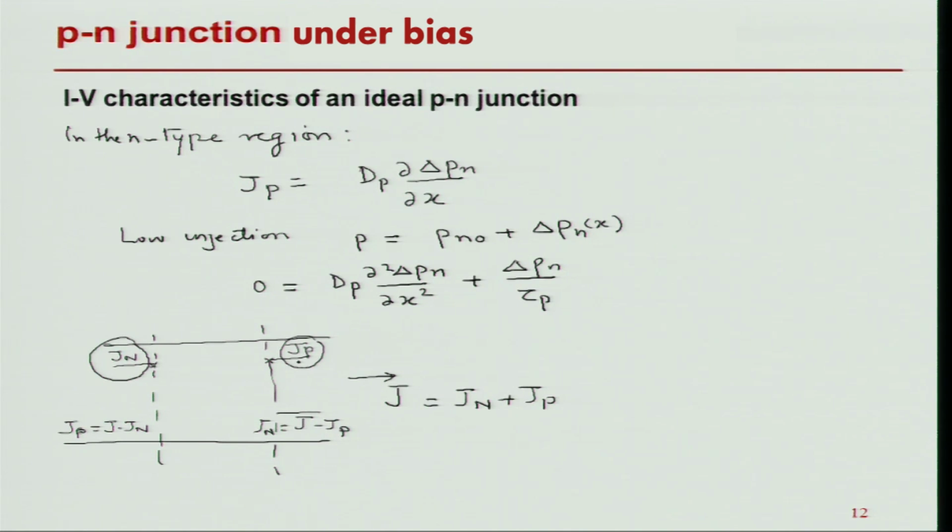All I am doing is injecting some little amount of carrier from P to N or N to P. And so, in the low injection regime, we are saying that whatever was status quo in the depletion region is maintained, and since there is no generation and recombination in the depletion zone, no generation of carriers, basically whatever current I am getting here for the electrons or for the holes is going to be the same in the depletion region.